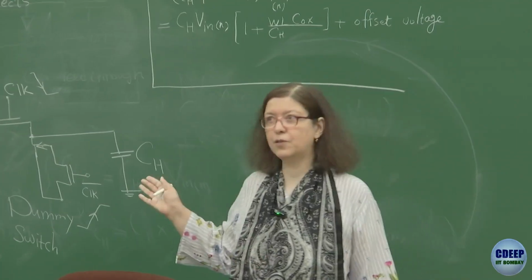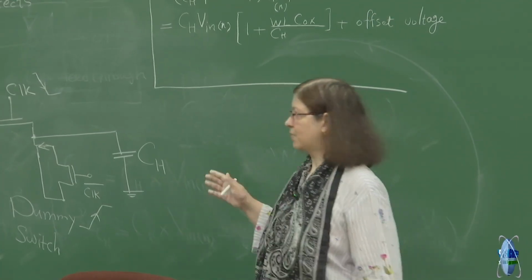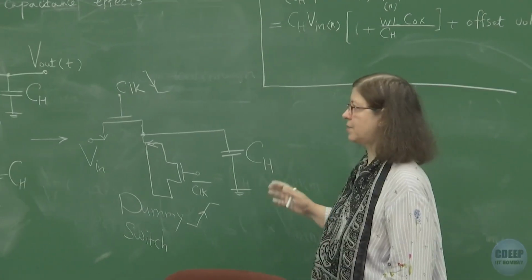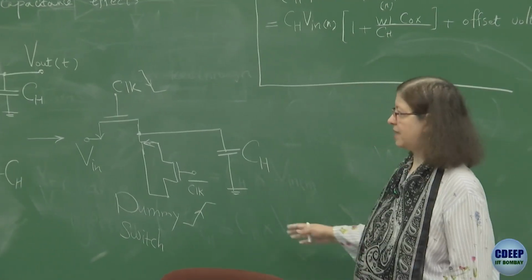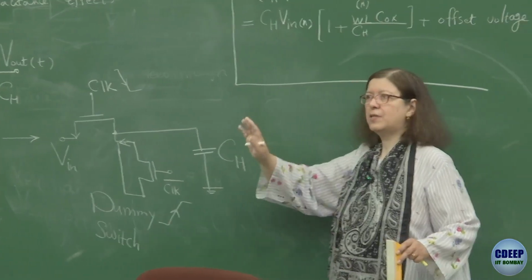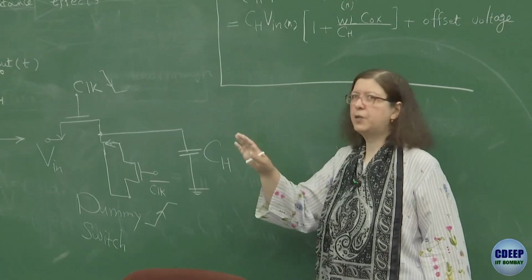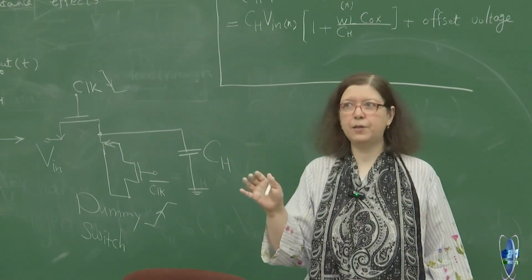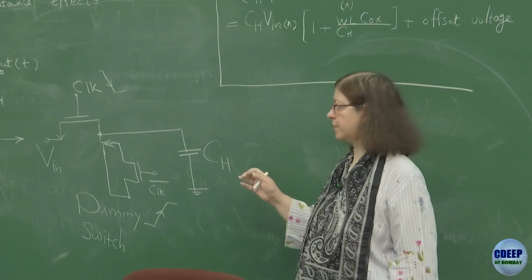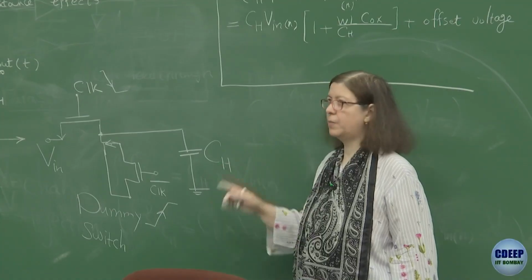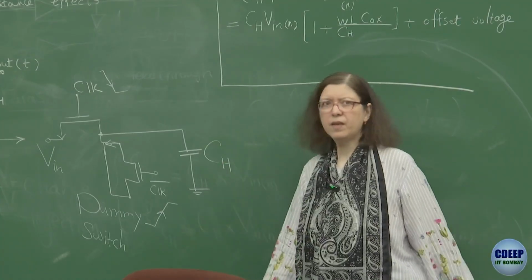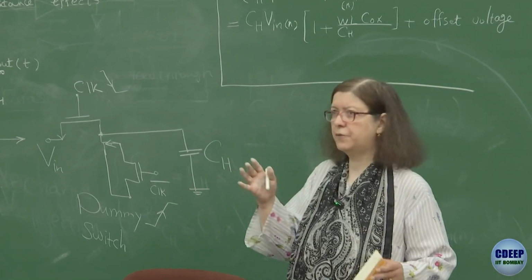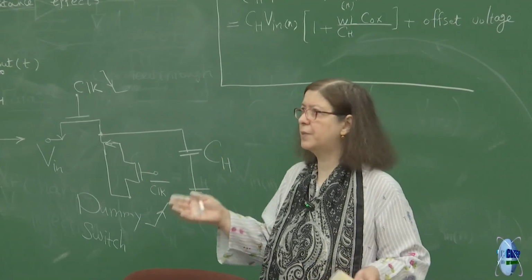Sometimes you see that it works very well, again, because, so it's very important to at least be consistent across all simulations and have enough precise simulations. First order simulations can be always in liberal mode of Spectre, making it fast just to get some idea. But when you want to actually see the effects, you need to do a very precise simulation. But because it's very time consuming and also creates a lot of data, transient files or PSS files become large.